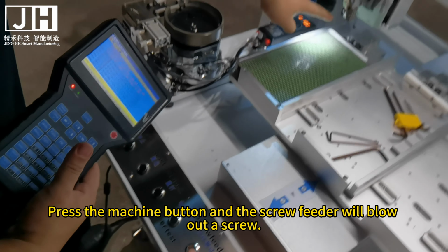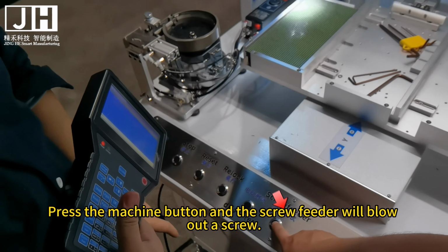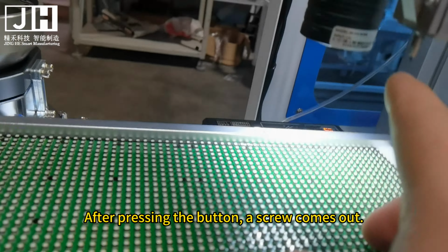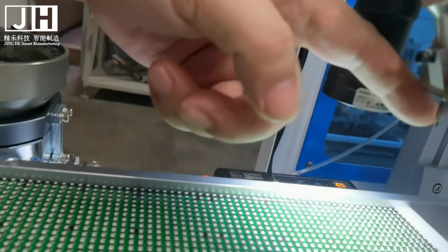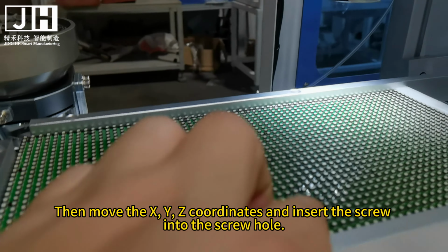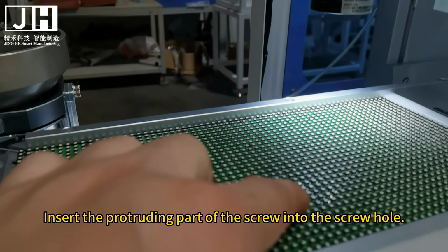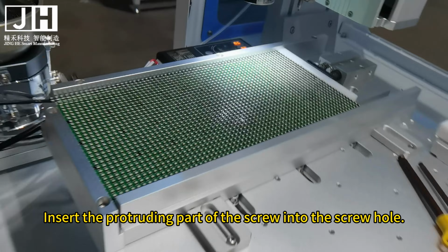Press the machine button and the screw feeder will blow out a screw. After pressing the button, a screw comes out. Then move the X, Y, Z coordinates and insert the screw into the screw hole. Insert the protruding part of the screw into the screw hole.